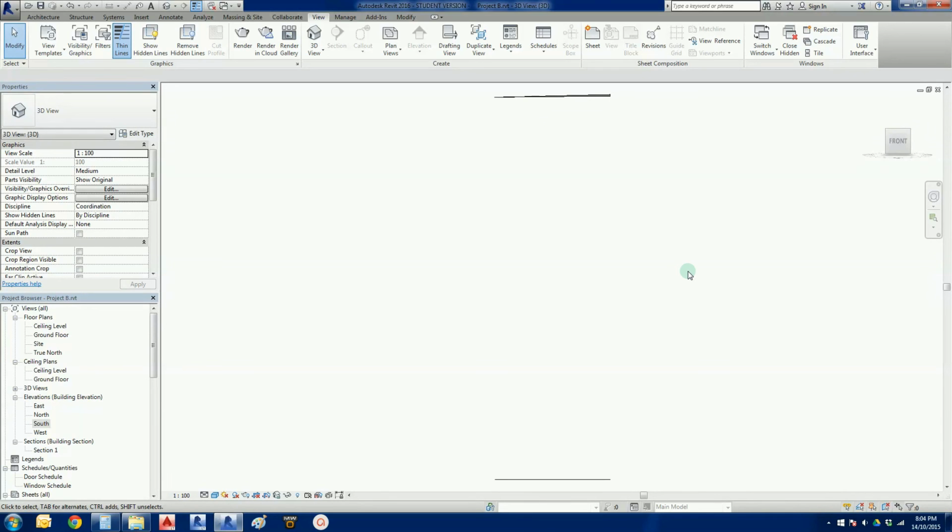So what I ask my surveyors before they're engaged to do a particular job is to set the datum at around about 10 meters. What that does is bring this all the way down here, a little bit more in line with my expectations of where a site is.